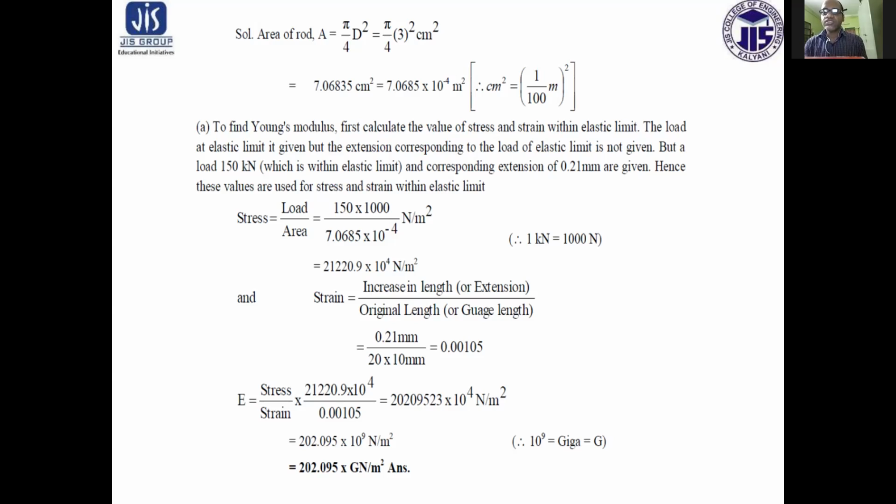So the stress, we know, is resisting load divided by area, that is the load applied, 150 kilonewton converted into newton by multiplying by 10 to the power 3, divided by the area in meter square.